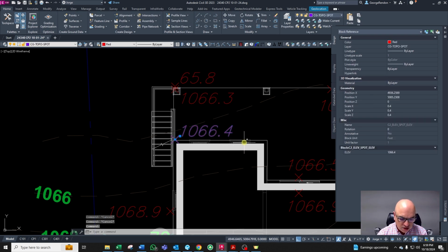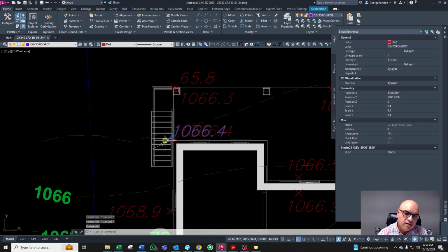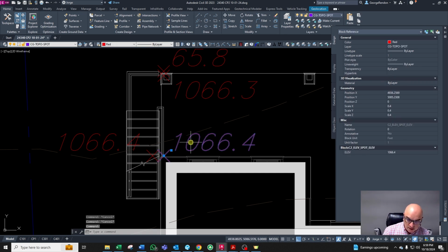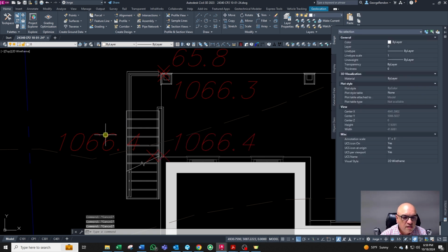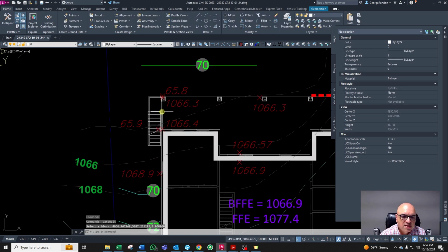As soon as you go down outside this patio, it is 0.5 feet, or 6 inches, below this elevation. So we're talking about 66.4 minus 0.5. This is 65.9. And that way we guarantee this is daylighted.